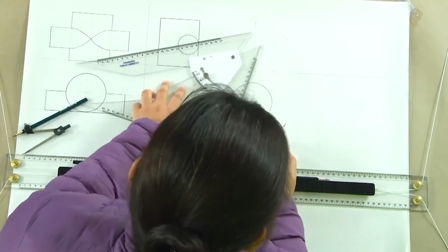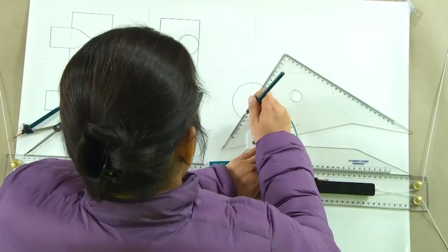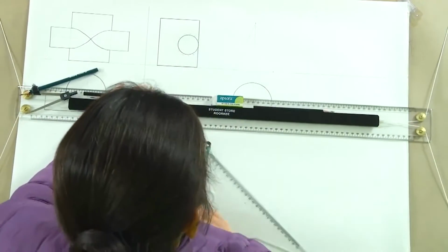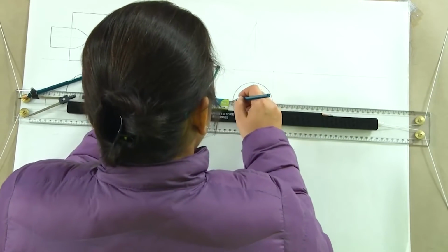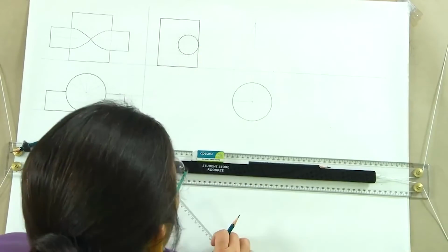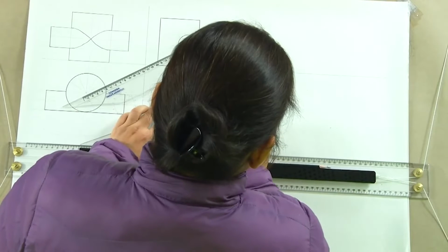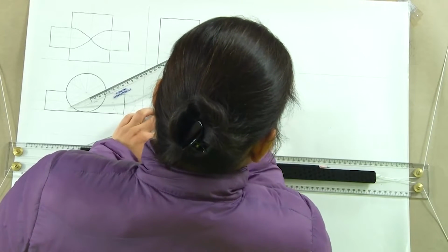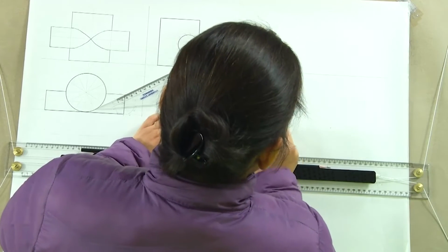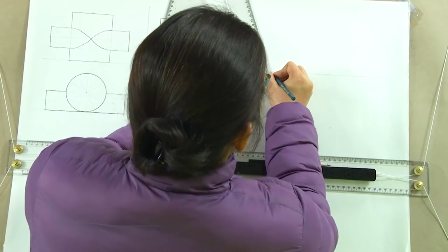So, we divide this base circle into 12 equal parts, and these all are going to be the generators of this cone. So, this is what the cone is, and we will just project these generators, just like we do whenever we draw for cones.